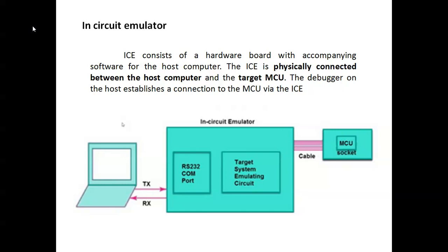In circuit emulator. So what is an in circuit emulator? They simply say ICE. It consists of a hardware board with the accompanying software for the host computer. That is an in circuit emulator. The in circuit emulator is physically connected between the host computer and the target MCU.